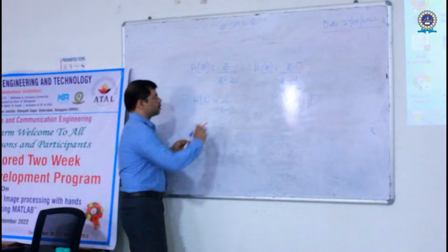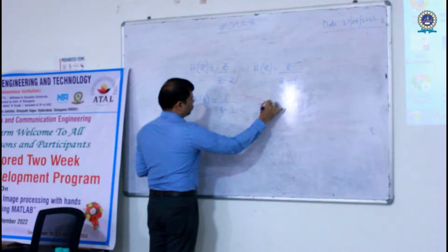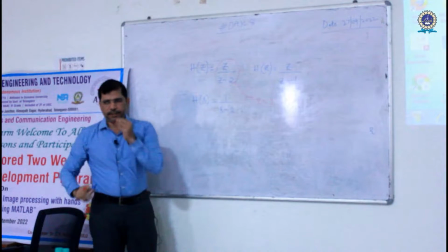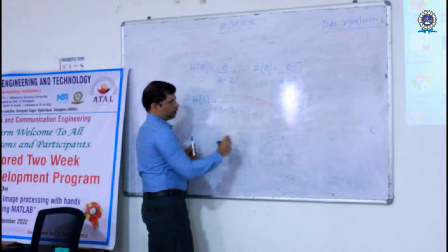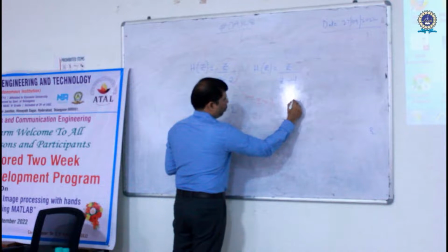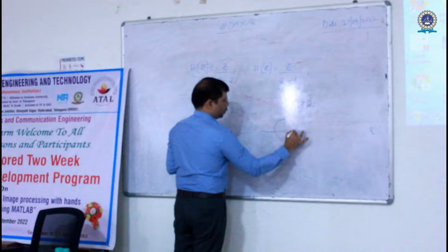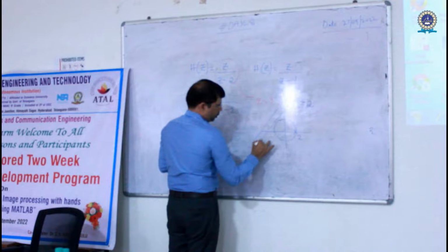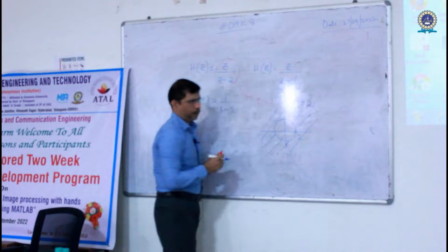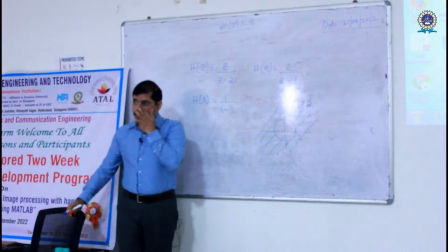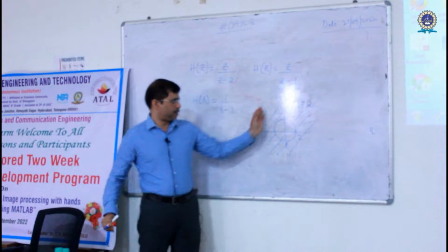So if you look at this kind of design, you can clearly understand that here you have the pole at Z equals 2. Now you have to normally decide the region of convergence. So if I assume that this is a causal filter, then in that case it's going to be mod Z greater than 2. So in that case, if you would like to plot the ROC, then it is above or outside 2. That's what this equation talks about, because you're talking about the causal. The causal filter is nothing but the one whose impulse response starts from n equal to 0, right? So normally it is outside the outermost pole.